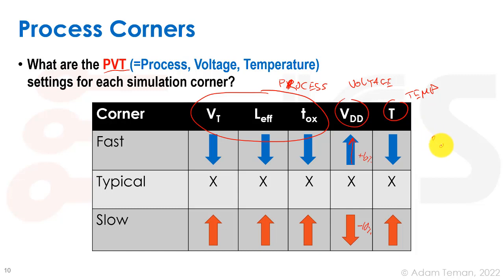For temperature, when we raise the temperature, we heat up the atoms in the channel. The atoms have this type of motion, Brownian motion, and they're moving around all the time. They have some probability of moving around, and the more energy we give them by more temperature, the bigger this gets. Then we have a nice little electron over here that wants to run from one side of the channel to the other. Since these atoms are moving around faster and all over the place, there's a higher probability that it's going to run into them and slow down its overall speed.